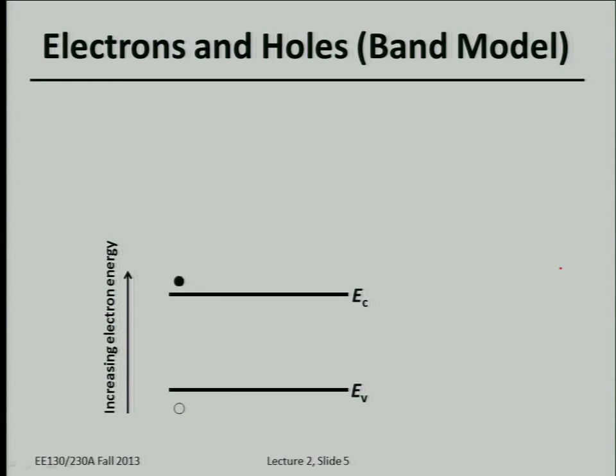And to illustrate electron-hole pair generation, like when Peng stood up, he actually occupied an allowed energy state as a conduction electron. Okay, and then leaving behind an empty state in the valence band, and that's why we use an open circle. But that's a hole that can now move within the allowed band. So remember, a hole moves due to electrons moving from one covalent bond to another. So a hole can move around within the valence band, just like an electron can move around within the valence band. Electron can move around within the conduction band as well.